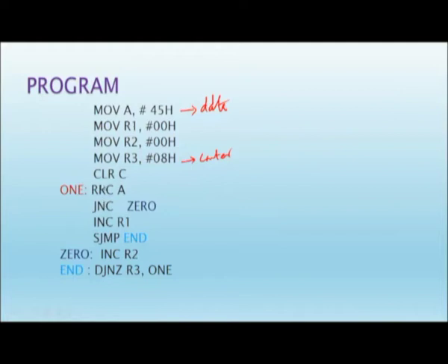First, it depends on the carry, so I am clearing the carry flag. Initially I cleared the carry flag. Now, the accumulator content is rotated right. So, what is your value? 0 1 0 0 0 1 0 1.